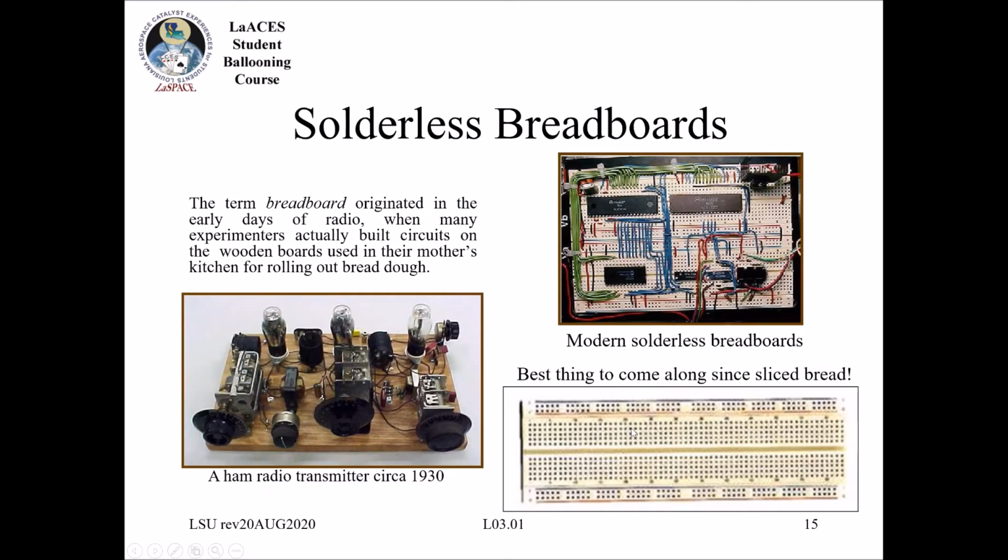If you ever pick up a breadboard, before you just start throwing stuff on there, I would recommend taking your multimeter and checking the resistance. If you're getting a low resistance across pins, that means they're electrically connected. If you're getting an open circuit or no resistance, that means those are electrically isolated. So you definitely want to understand how that breadboard is laid out before you go and hook it up. You can get those at any electronics store, and they're very useful to hook up basic circuits.